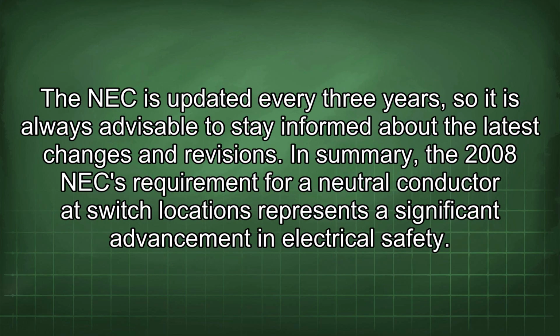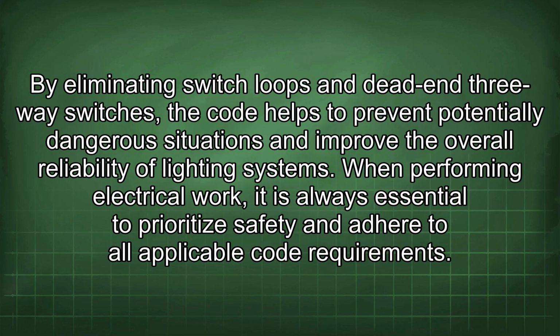The NEC is updated every 3 years, so it is always advisable to stay informed about the latest changes and revisions. In summary, the 2008 NEC requirement for a neutral conductor at switch locations represents a significant advancement in electrical safety. By eliminating switch loops and dead-end three-way switches, the code helps to prevent potentially dangerous situations and improve the overall reliability of lighting systems.